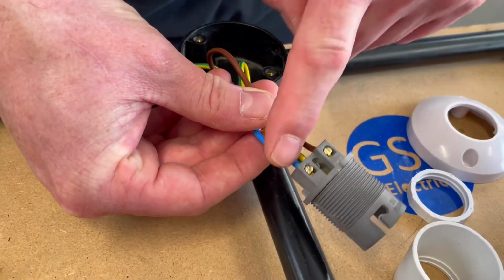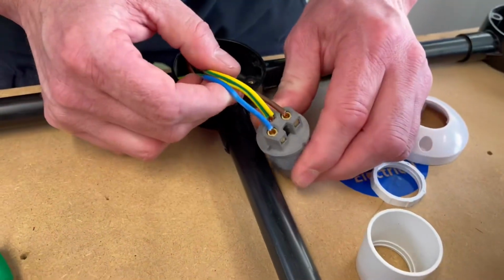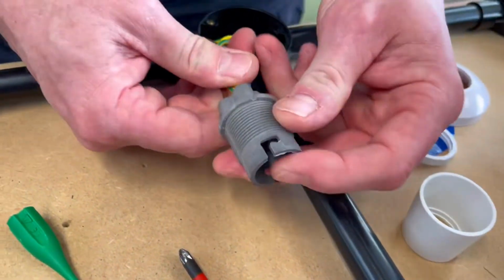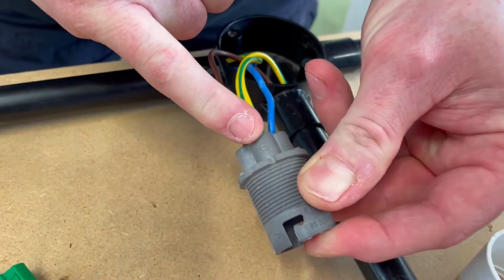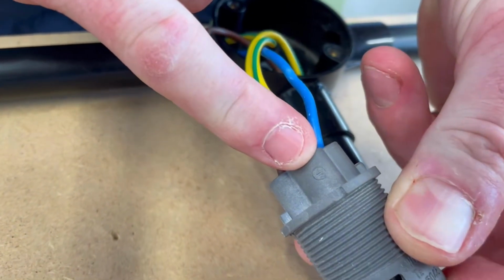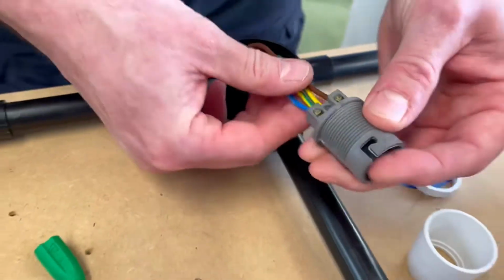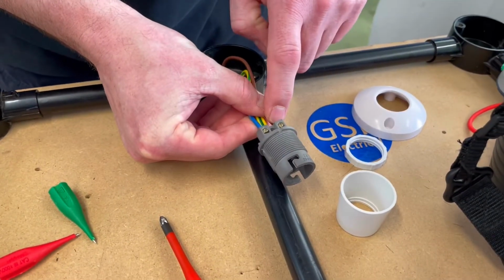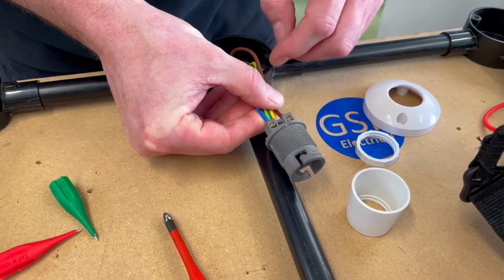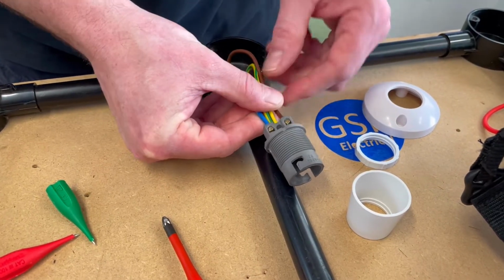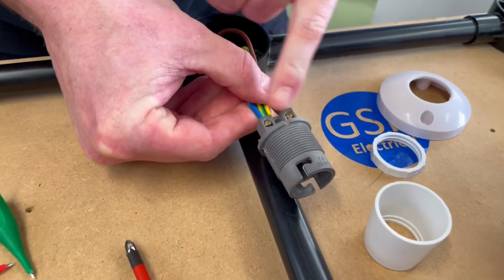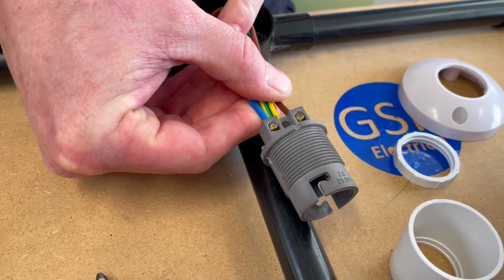So there's no polarity to these, but it's deadly important that we got the circuit protective conductors in the right place. And hopefully you can just see there the symbol for earth. So our CPCs were connected in the back section, but we didn't have an L and an N or an SL and an N for our switching line and neutral connections. So it doesn't matter which way around we have them. So we've got no polarity at this lamp holder.